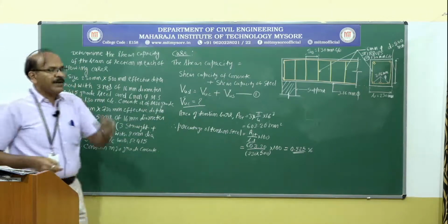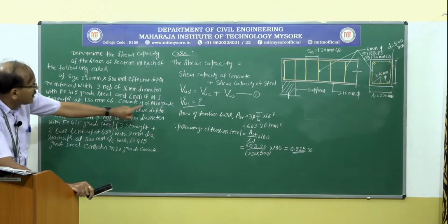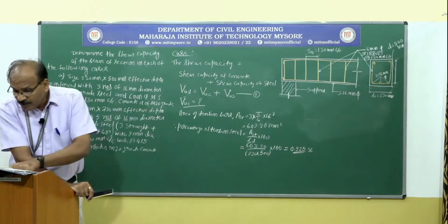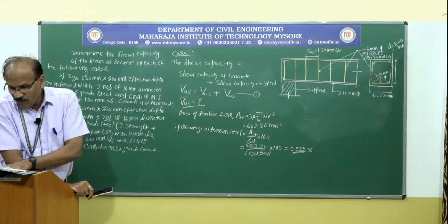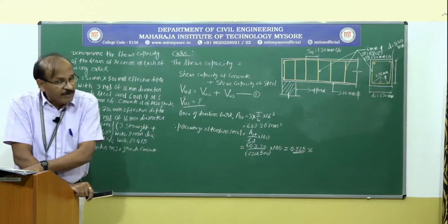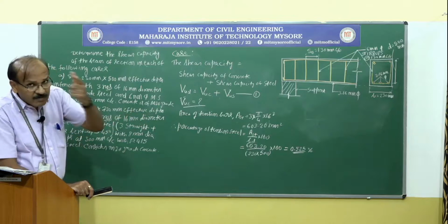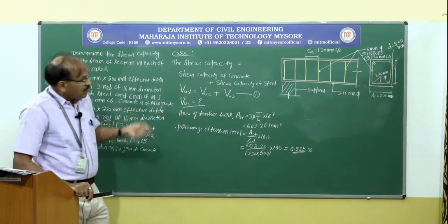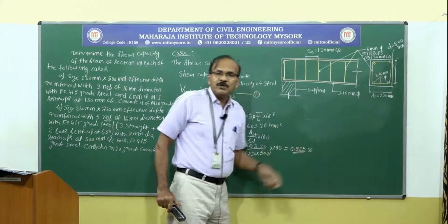So go to table 19, page 73 of the code book, and the type of concrete we are using is M20 grade. So for M20 grade, for 0.525, do we have a value? No, we don't. We have a value for 0.5 and we have a value for 0.75% of the steel, which is equal to 0.56, and 0.525 comes in between those two. So I am going to do some linear interpolation to find out the shear capacity or shear strength of concrete corresponding to the steel area of 0.525%.